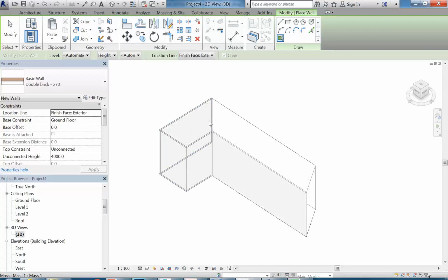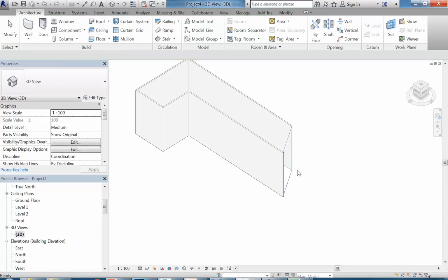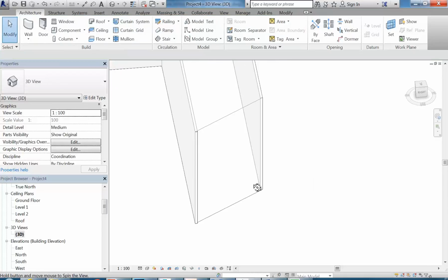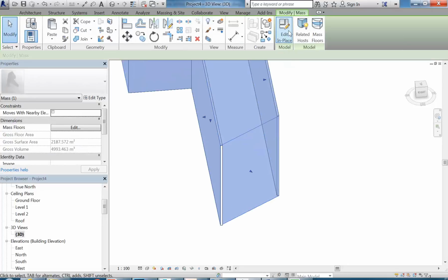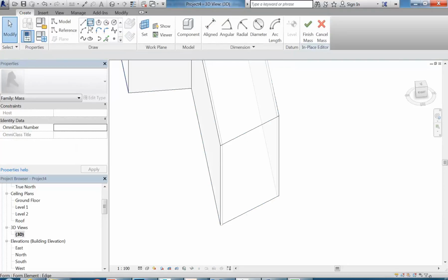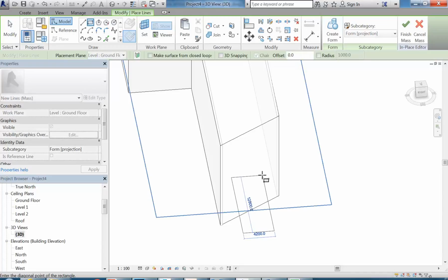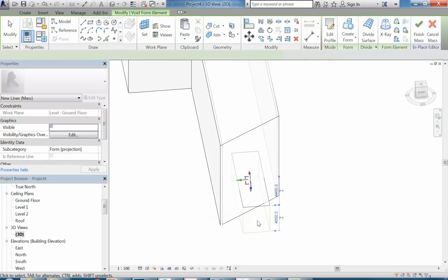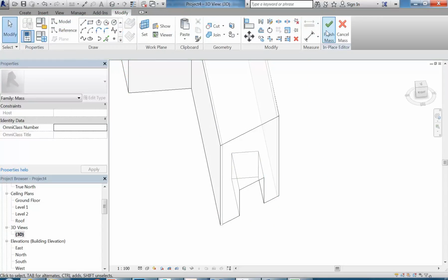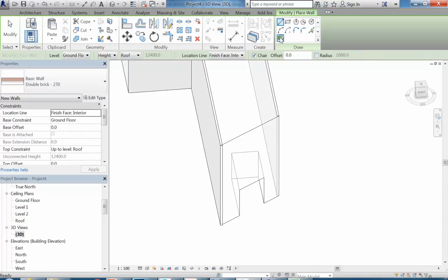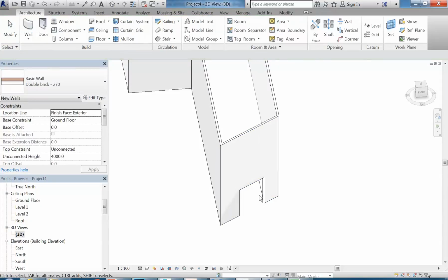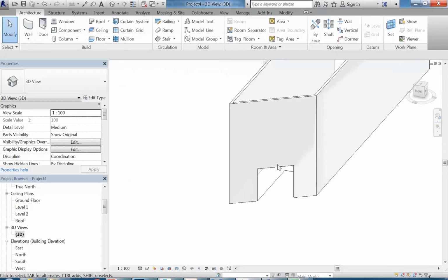Right, so that's easy. Once you've got the mass in there, if you're going to use massing, you don't have to, but it can make things easier. And, oh yeah, so that mass there, I might decide, well, okay, I want to make some more detail there, so I'll put a void in, just for something there at the front. Just cut a hole out of it, and so then if I go and make a wall, now, using that surface, it'll obviously have that hole already done.